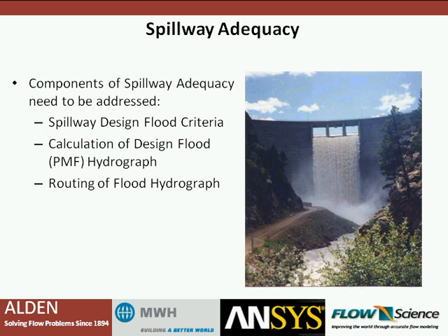Another factor, of course, is once you've decided on what that flood is going to be, whether that's, say, a 100-year flood or a 1,000-year flood or some other flood, the actual calculation of that design flood itself. And typically, the maximum flood that we design for is the PMF, or the probable maximum flood. And there's a hydrograph that goes along with that that dictates the volume of water and the amount of water that